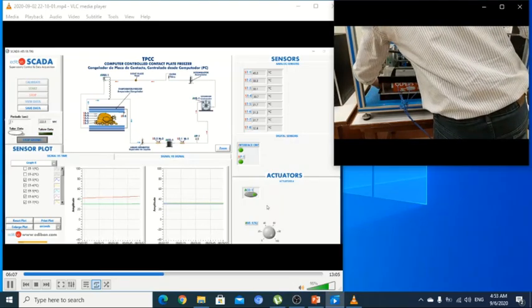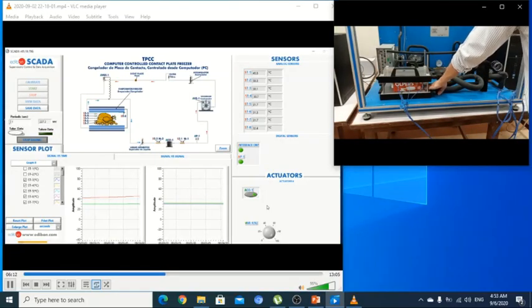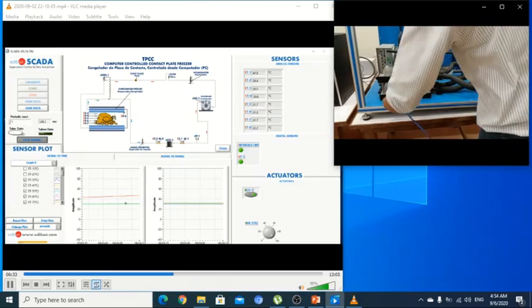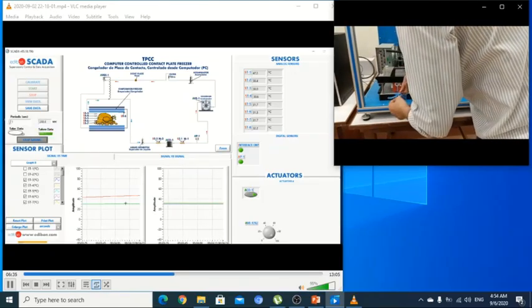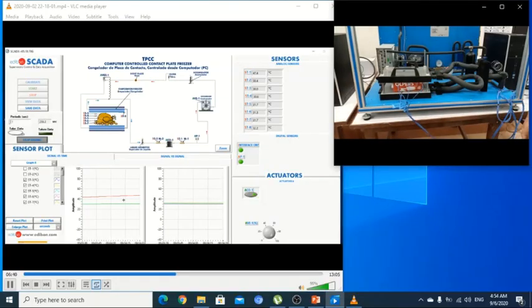At 30 degrees centigrade the condensation may occur at 1600 kilopascal, but if the environmental temperature is 40 degrees centigrade, the compressor needs to compress the refrigerant up to 2000 kilopascal. So that is a remarkable increment just because of the environmental temperature. That's why in hot conditions like nowadays, the refrigeration cycle won't work so effectively.